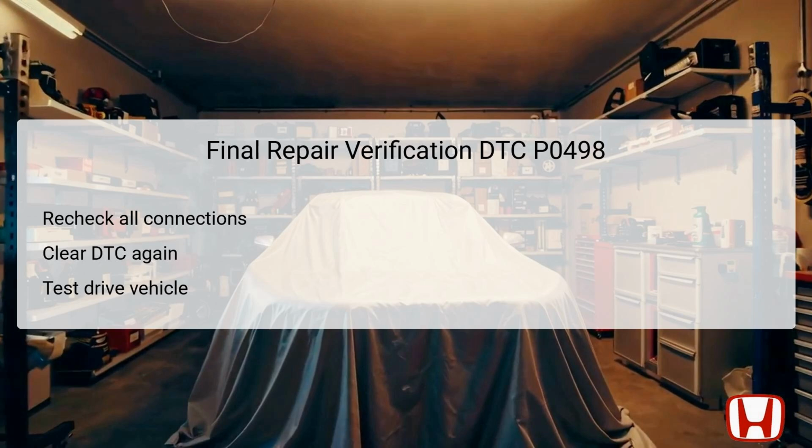It's essential to conduct a test drive under varied driving conditions to monitor for any reoccurrence of DTC P0498 or any related symptoms. During this test drive, pay close attention to how the vehicle performs, especially regarding fuel economy and any abnormal odors. If the check engine light does not illuminate and performance is normal, you can confidently conclude that the issue has been resolved. Documenting these findings is also valuable for future reference and potential warranty claims.